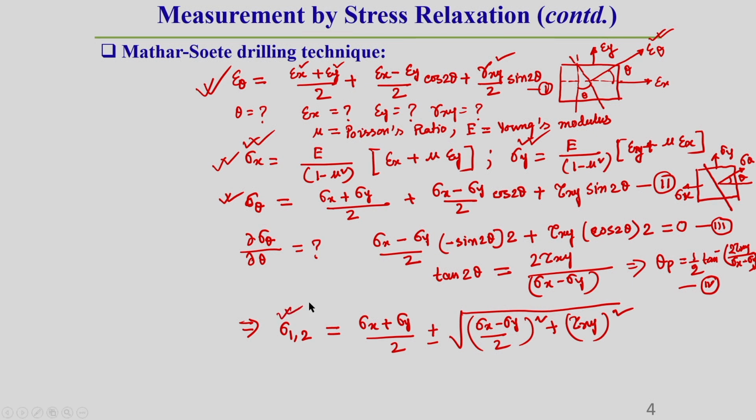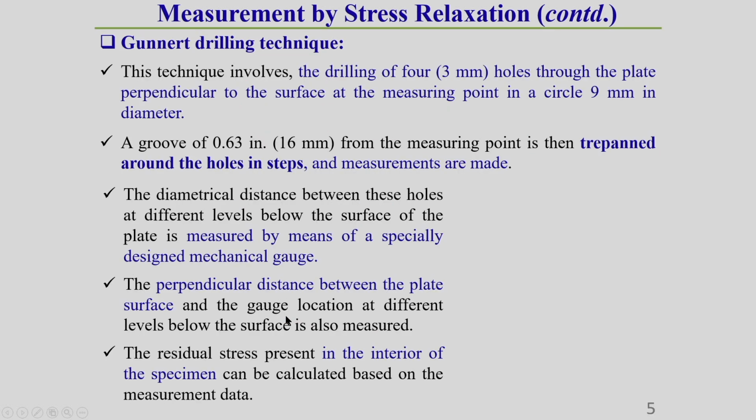So, what is the maximum residual stress that exists in the specimen, in that welded specimen, whatever the specimen it is, that we can easily find out by this relationship. Now, we will discuss another stress relaxation residual stress measurement technique, that is called the Gunnert drilling technique.